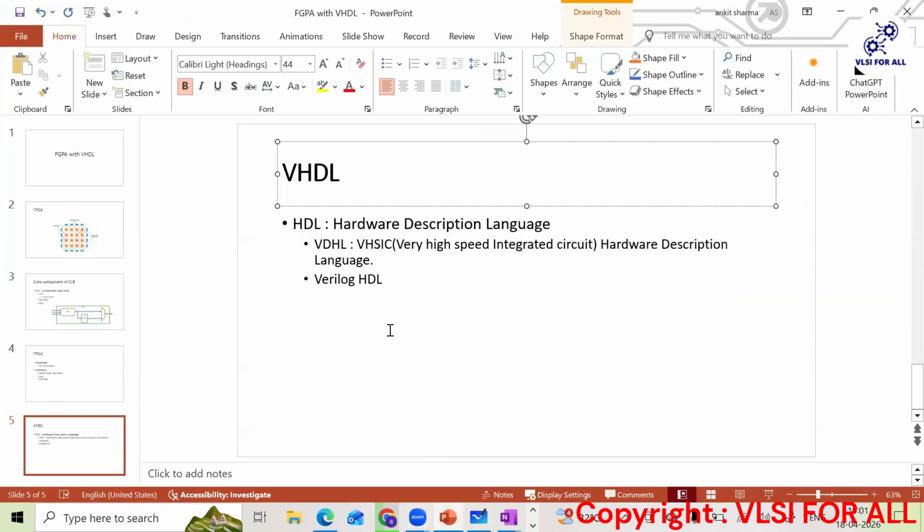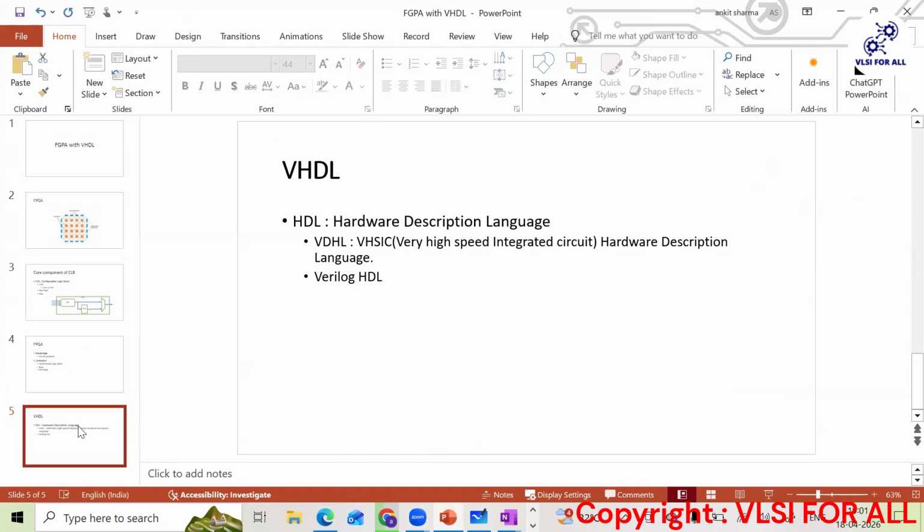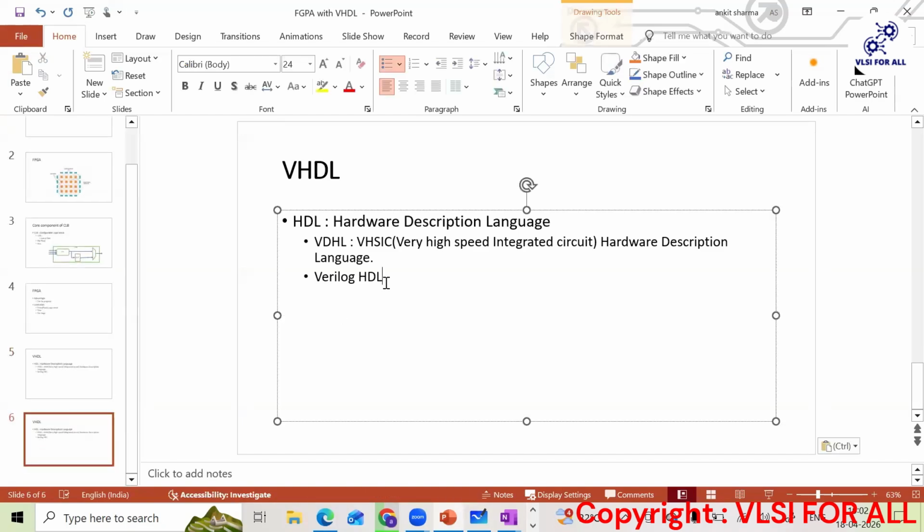So yesterday we discussed regarding this FPGA and this VHDL, how they are having a relation and how we'll use this VHDL in FPGA. So later on, after getting the netlist, with the help of other software we need to convert that netlist to bit stream, and then that bit stream can be burned into our FPGA. So then the same FPGA board can work as that design, whatever we design in the VHDL language. Okay, so let's see next.